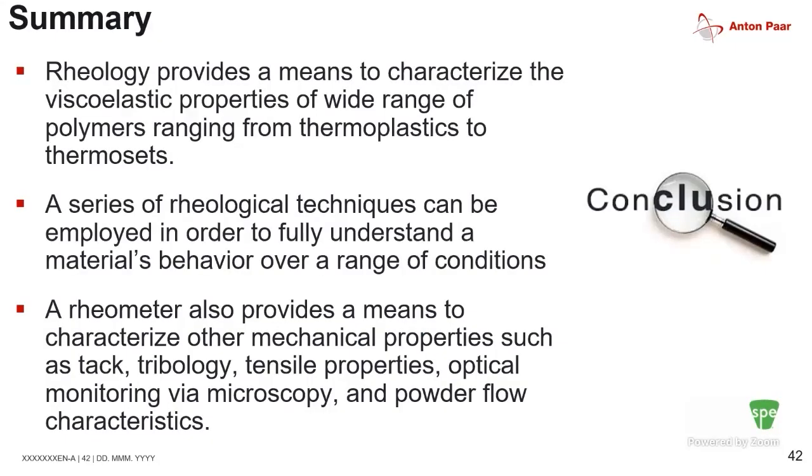with that, hopefully you can see that rheology provides a means to characterize viscoelastic behaviors, to understand polymers, not just from a fluid standpoint, but also to understand their elasticity, whether it be a thermoplastic, a thermoset, or a thermal resin, as well as using these various techniques that you can employ to fingerprint your material under different conditional responses.